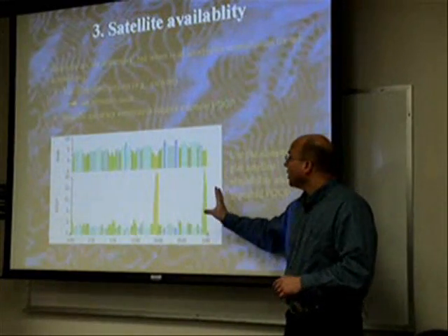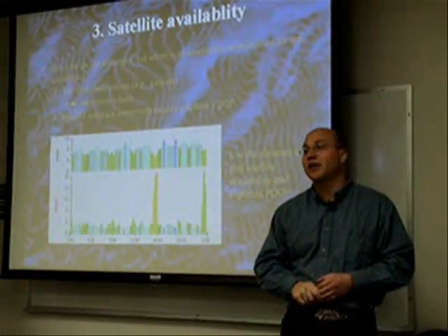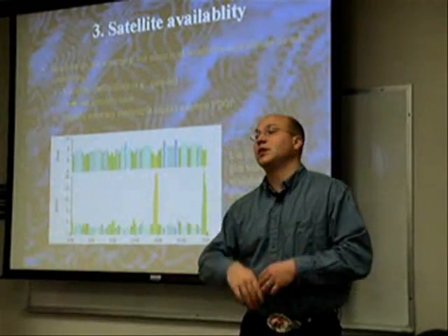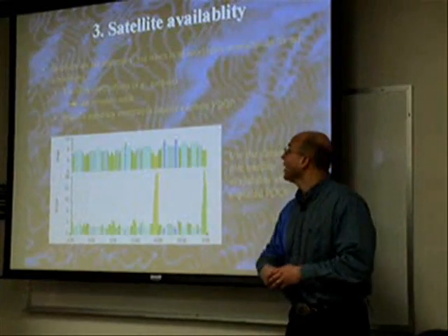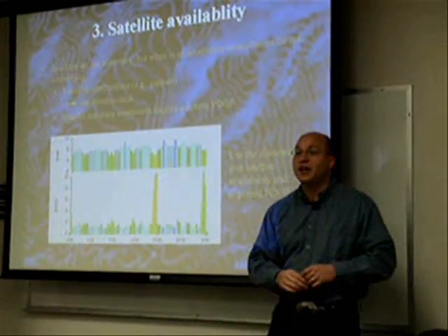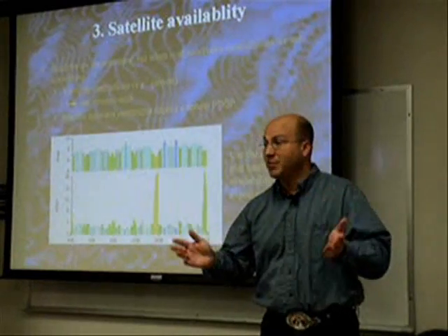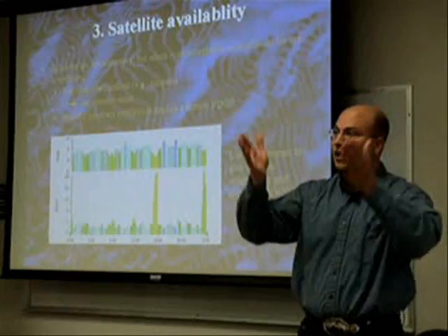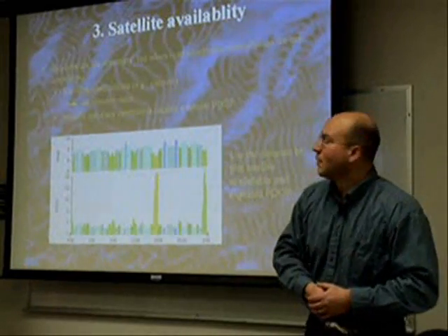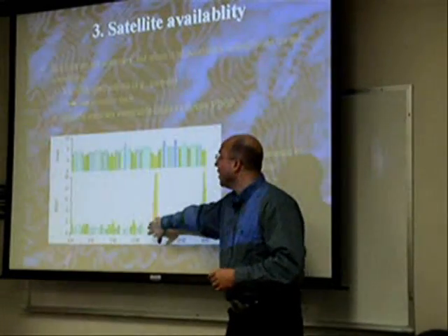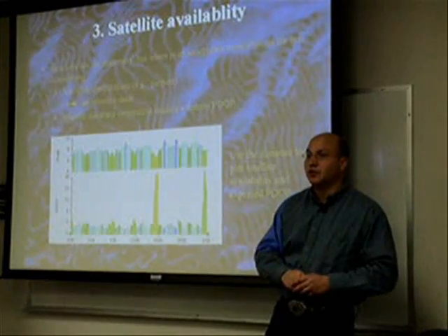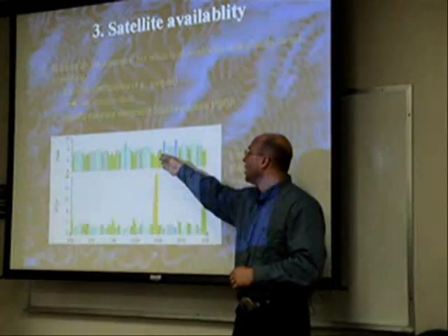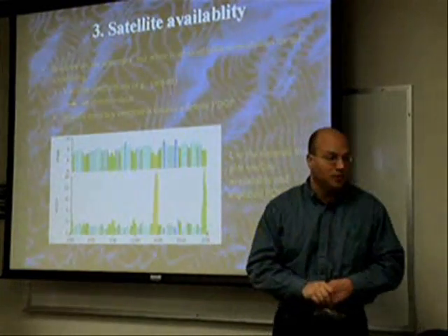This program also allows you to insert an elevation mask, basically what we referred to back up here in your valley. So you can basically mimic the situation you will find out there using that elevation mask. And then it will show you when you have a PDOP that is suited to you. And here, the number of satellites that are available.